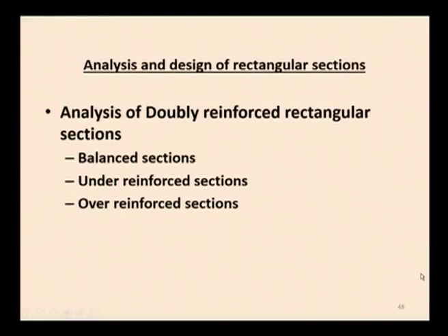Due to the reinforcement of the doubly reinforced rectangular section, the moment of resistance can be increased without altering the dimensions of the section. So, due to structural or architectural considerations, the section will have insufficient area of concrete to provide for compressive stresses when you reduce the size of concrete. So, steel is placed in part of the compression zone in order to supplement the concrete in resisting the compressive stresses. When you provide reinforcement at the top, that is, in the compression zone, the section becomes a doubly reinforced rectangular section. Here the moment of resistance can again be increased without altering the dimensions of the section.